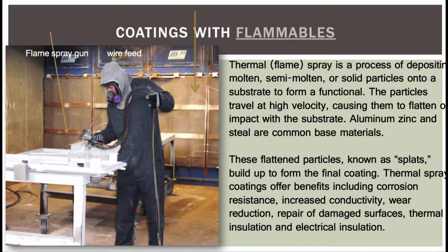So also covered under the OSHA rule is spray finishing with flammable material. And this is a thermal flame spray process where you deposit molten and semi-molten particles onto the surface. And again, this is a Navy operation, and they were covering these watertight doors. The particles travel at high velocity and they flatten on the surface, providing a nice coating or sealing, so it seals it together. And these flattened particles are known as splats, and they build up along the outside of the surface.